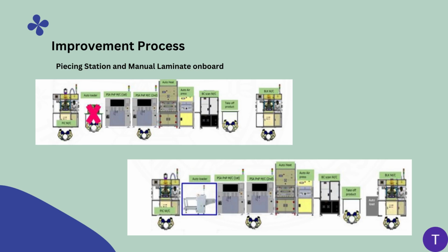And in station 2, the worker will put the sheet on the board. After we adjust station 1, we put in a slide rail for the output and a design base that can fit a product, or we can call it a magazine. Then we add an auto loader that can load the magazine into the process, which helps eliminate station 2.